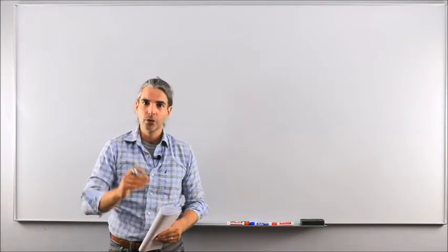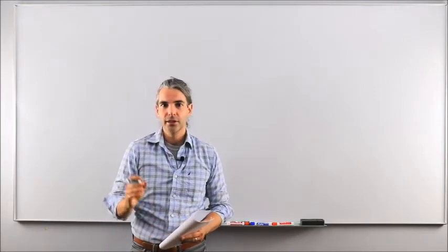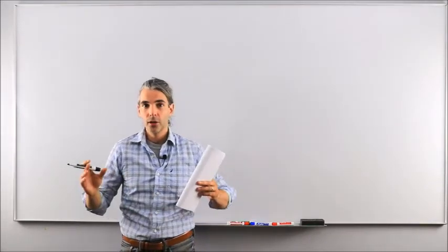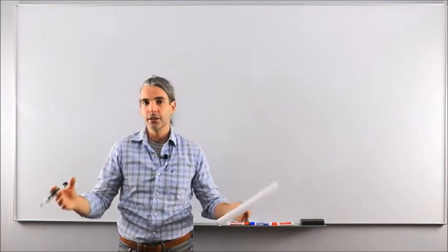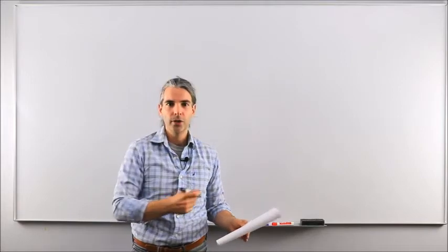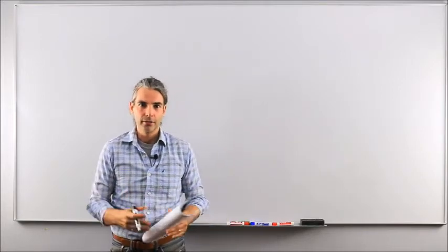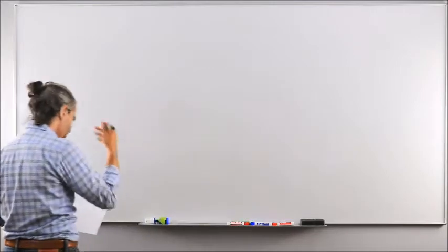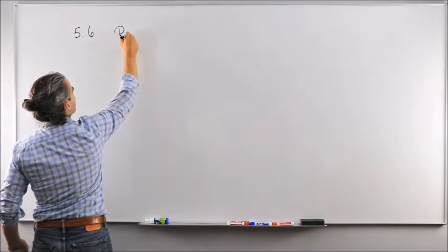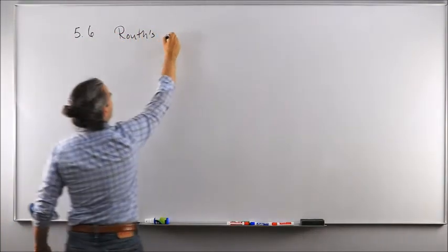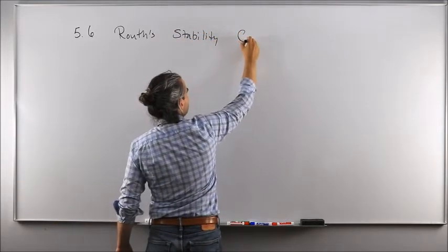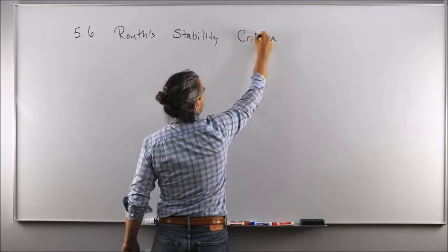Now today, the tool we're going to talk about, Routh stability criteria, we need the closed loop transfer function because for practical purposes, we'd like to analyze the asymptotic stability of the closed loop transfer function. The stability of just the open loop is not of our concern here, okay? So let's just keep that in mind as we move forward. And that'll be in 5.6. So, Routh stability criteria.